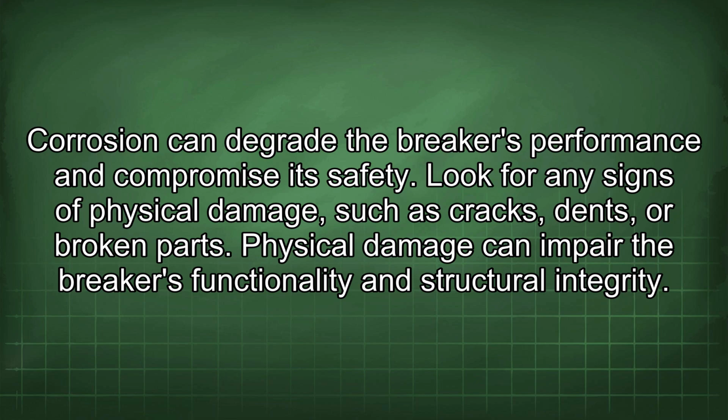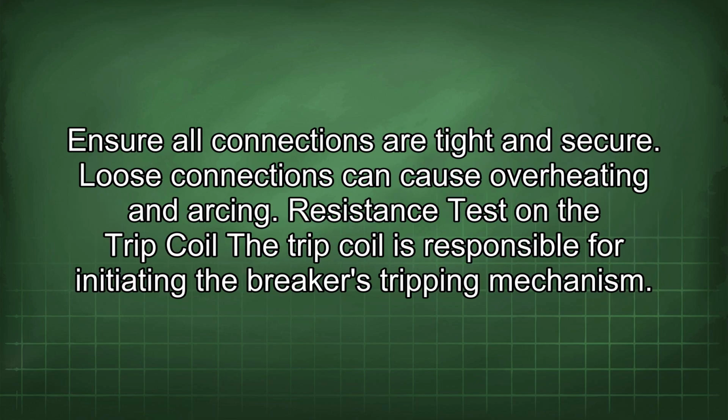Look for any signs of physical damage, such as cracks, dents, or broken parts. Physical damage can impair the breaker's functionality and structural integrity. Ensure all connections are tight and secure. Loose connections can cause overheating and arcing.